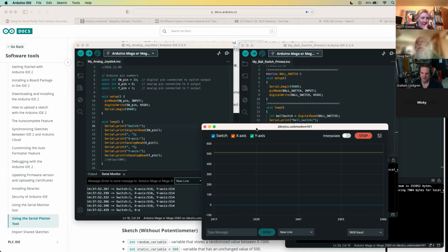I guess you'd just be pulling the joystick that much faster. Right. Well, we're just going through this loop function as fast as we can, and really the limit right now is how long it takes to actually do these digital reads. But one thing to note, Doug, as far as upping the ante on the baud rate for any of this hardware, you need to look at the specifications, the range of baud rates that is compatible with that particular part.